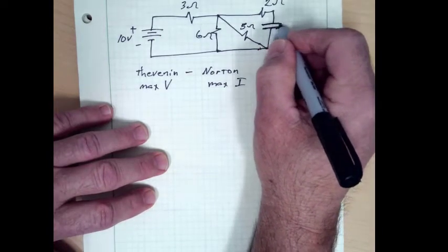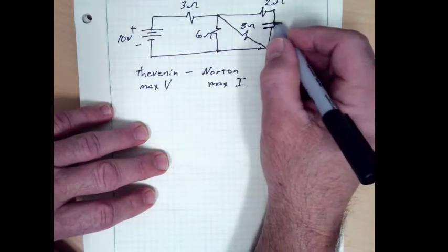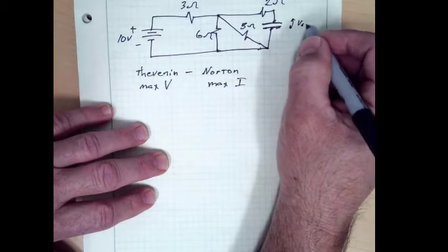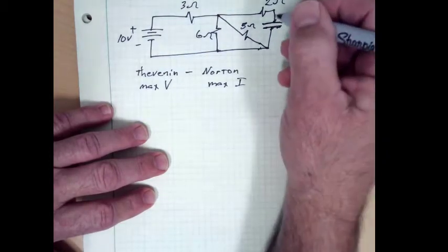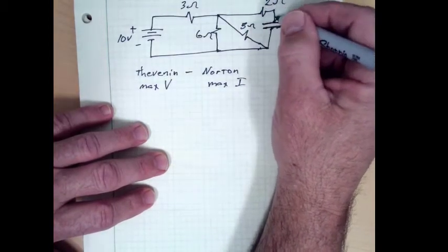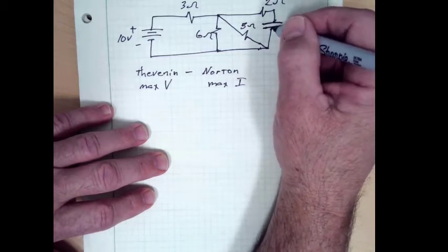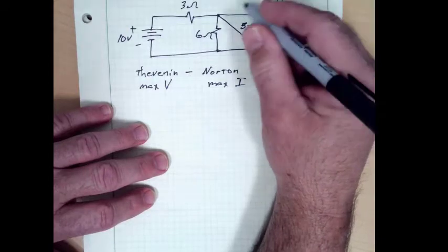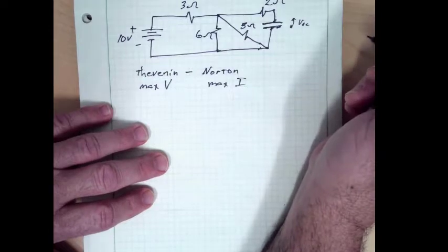And so Thevenin wise, we need to model this circuit as an open here at this point. In other words, find the open circuit voltage or the Thevenin voltage. And then we also need to be able to model the maximum current to the plates. The current does not go through this space, but the current builds by pulling electrons off one side of the plate and stacking them on the plate on the other side of the capacitor.